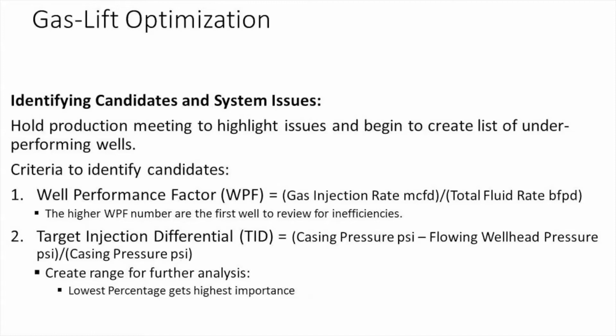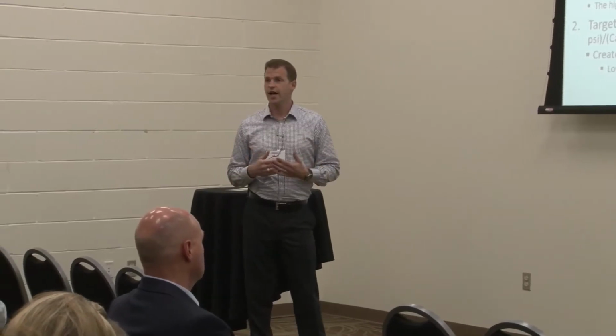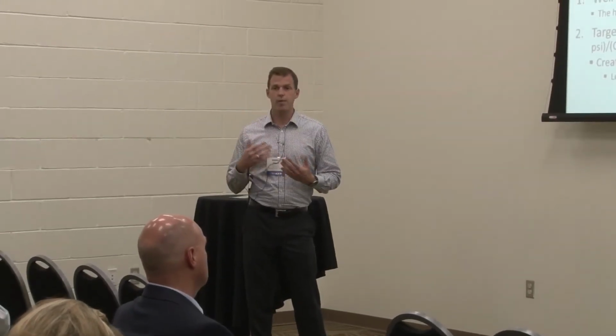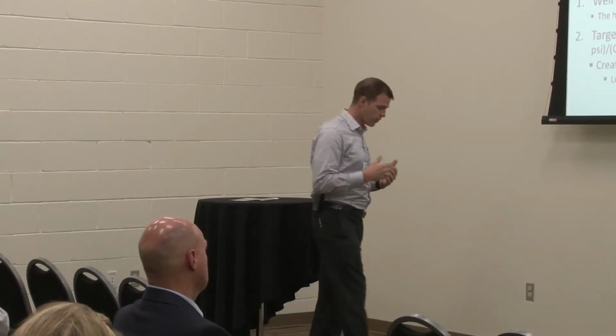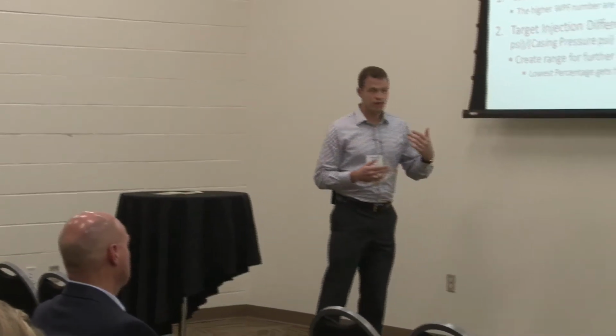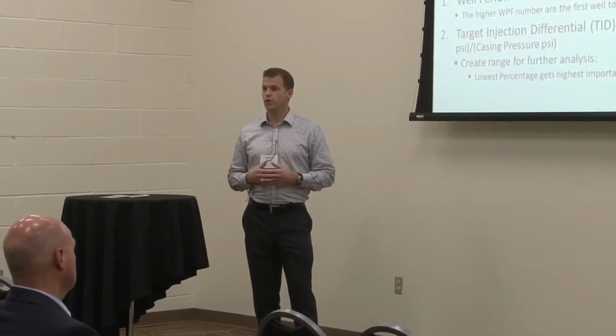When we're looking at our well performance, we're simply looking at utilization of injection gas versus return. How much total fluid are we getting back from the well? And the way we prioritize that is we're looking for over-injection, using too much gas to get very little fluid back.